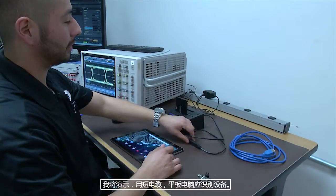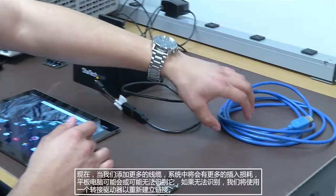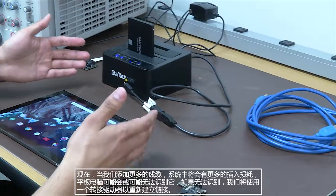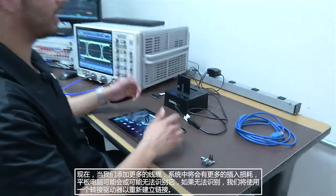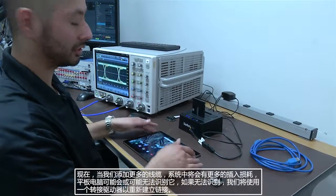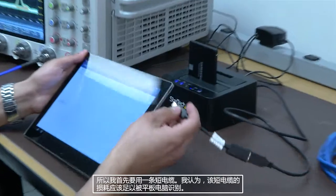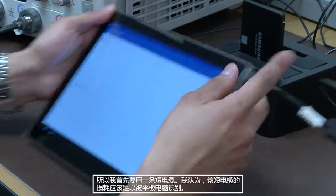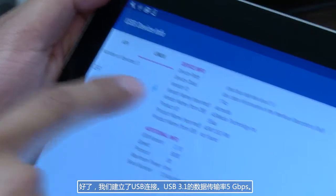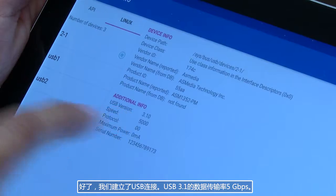I want to show that with a short cable, the tablet should recognize the device. Now when we add more cabling, more insertion losses are added to the system, and the tablet may or may not recognize it. If it does not, we will use a redriver to reestablish the link. So first I'm going to start off with a short cable. I believe that the losses of the short cable should be low enough for the tablet to recognize. And there we go. We made a USB connection, USB 3.1 at a 5 gigabit per second data rate.